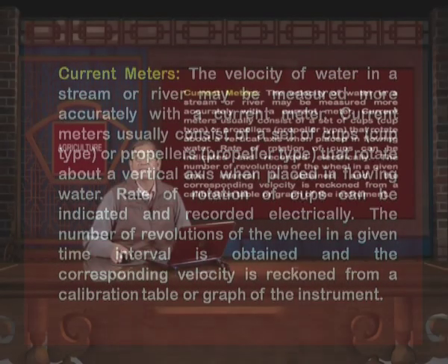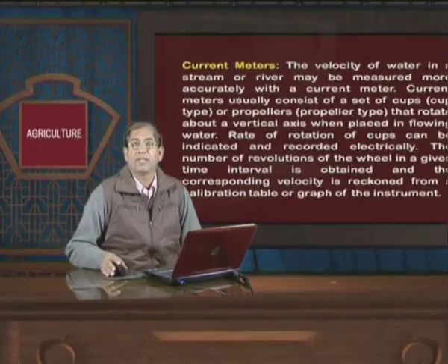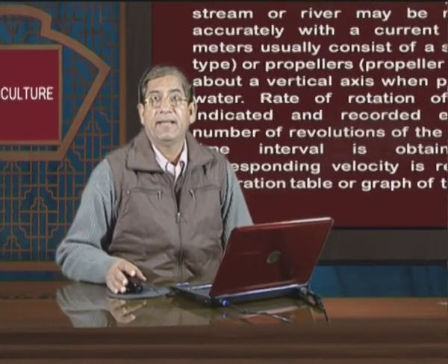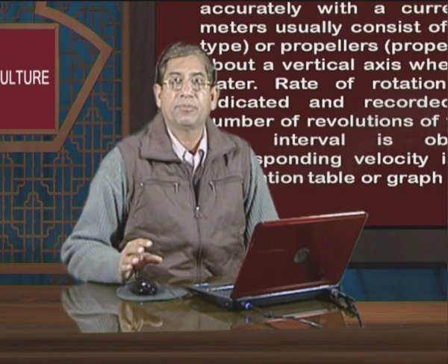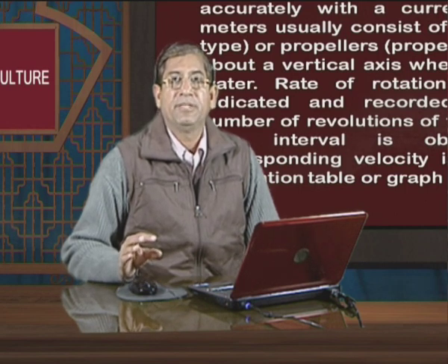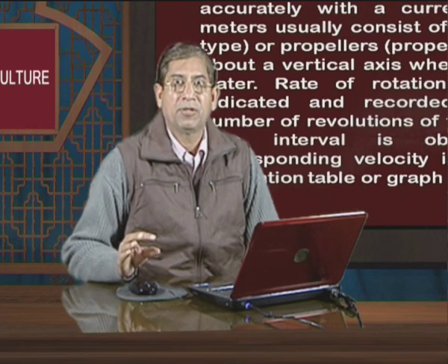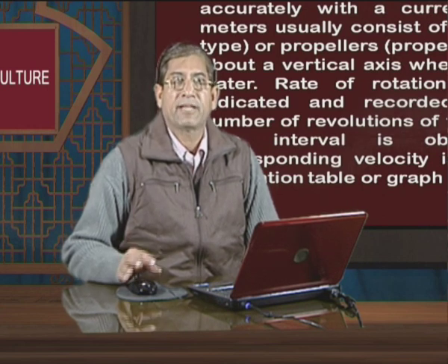So, the current meters are used when more accuracy is required, and again it is kept in mind that the current meters are placed in the middle of the stream. It should not be kept on one side of the stream or the other side of the stream.